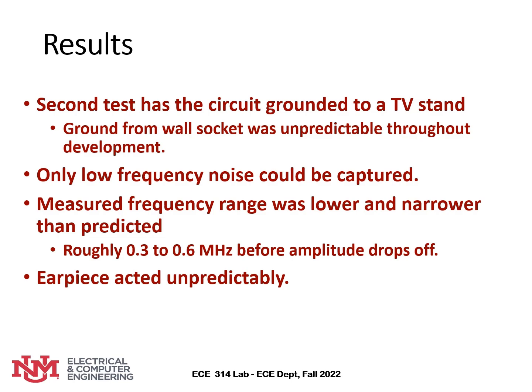So these are my results. The second test had the circuit grounded to a TV stand. I found throughout trying to test this that ground from the wall socket was really unpredictable and wasn't really giving me good results. File cabinets, TV stands, and metal bookcases all worked much better than ground from a wall socket.